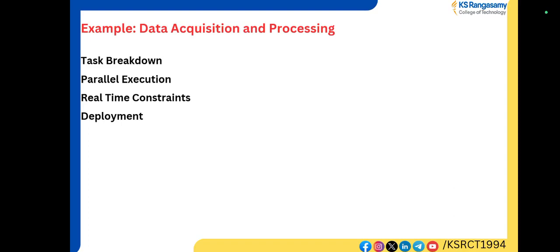PC through the DAQ. Now we have to break down the tasks to run in parallel. First thing, we have to acquire the data from sensors. The next task is we have to process the data and analyze it. The third one is we have to store the data and prepare the report. So in this way, we can break the huge tasks into simplified tasks, like acquiring the data as a task and transferring the signal to the DAQ is a task, from the DAQ to PC is a task, as well as computation is a task. Similarly, we can divide the large tasks into simplified tasks.